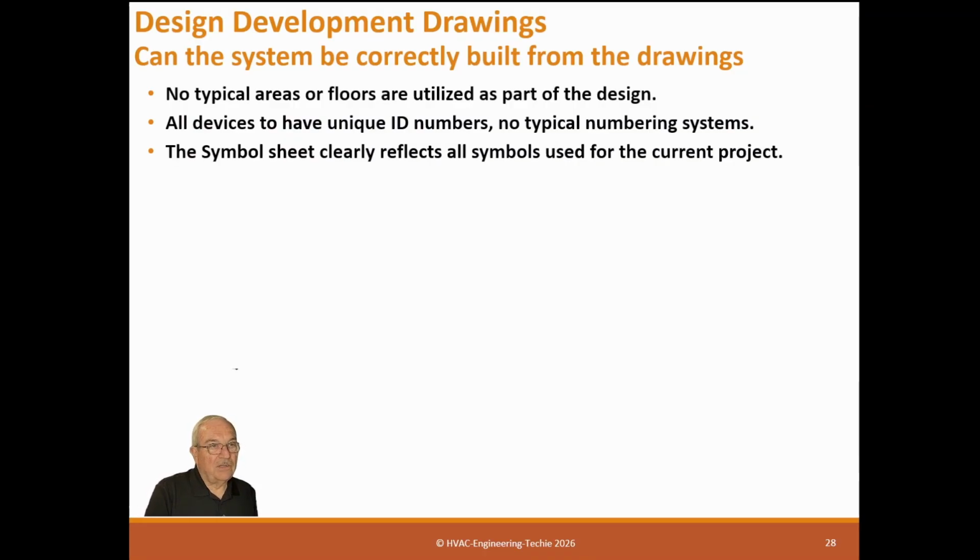The symbol sheet clearly reflects all symbols used for the current project. Here's the problem of using a standard sheet. Many times I'll look at a sheet and say, well, what is that? And I go to the symbol sheet, and it's not there. Or that symbol was used for something else. The symbol sheet needs to reflect the drawings. So that's something you need to look at.